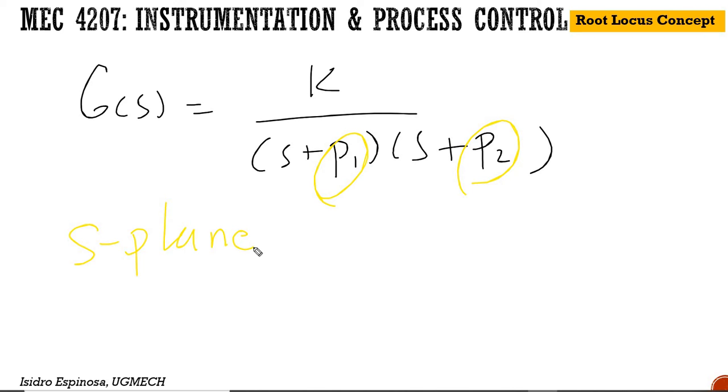The locus of roots of the characteristic equation of a multi-loop system, for example, may be investigated as readily as the single loop system. If the root locations are not satisfactory, the necessary parameter adjustments often can be readily ascertained from the root locus.